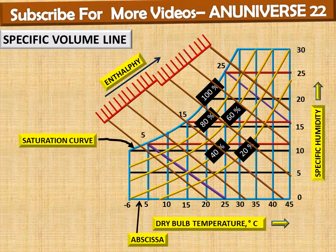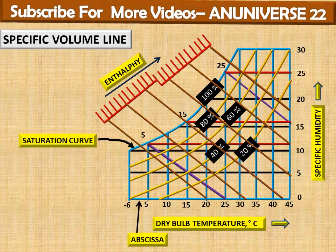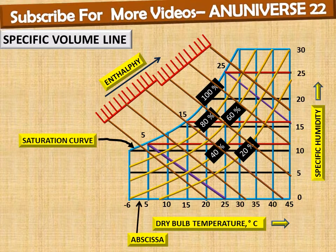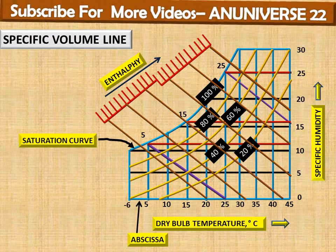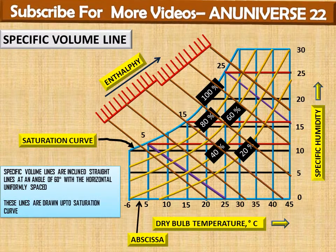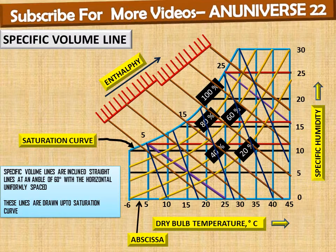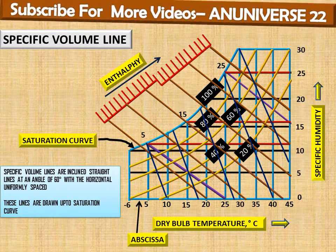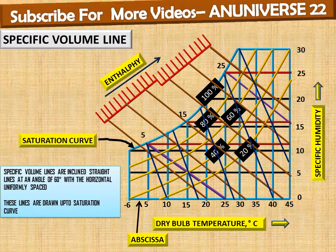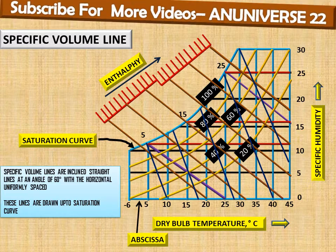Next is specific volume lines. Specific volume lines are inclined straight lines at an angle of 60 degrees with the horizontal, uniformly spaced, and these lines are drawn up to the saturation curve. So these are the specific volume lines, and the values of the volume lines are given at the base of the chart, the abscissa, in meter cube per kg of dry air.